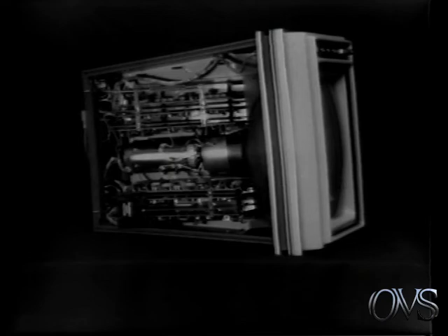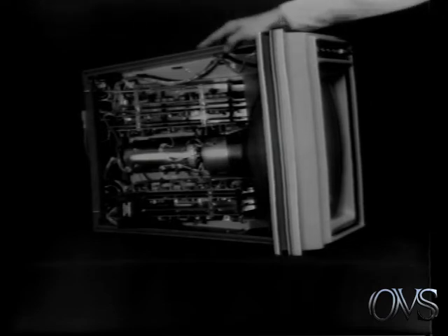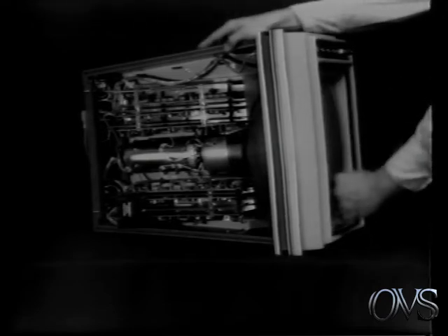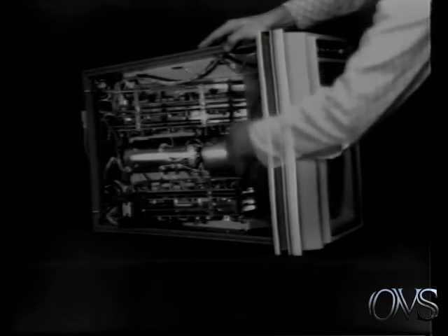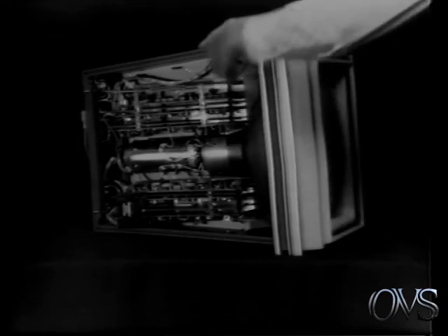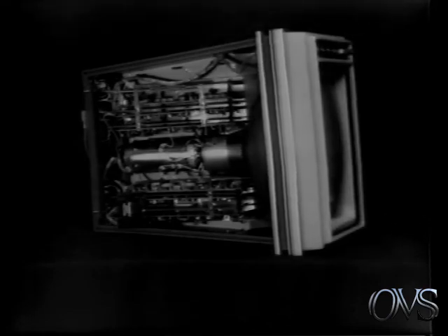Now let's discuss unique adjustments. First, remove the static charge that's present on the CRT glass. With power on, hold the chassis with one hand and rub the other hand across the face and top of the CRT. This eliminates being surprised by a low current arc later. This charge can't hurt you, but it is unpleasant and might cause you to jerk while making an adjustment.